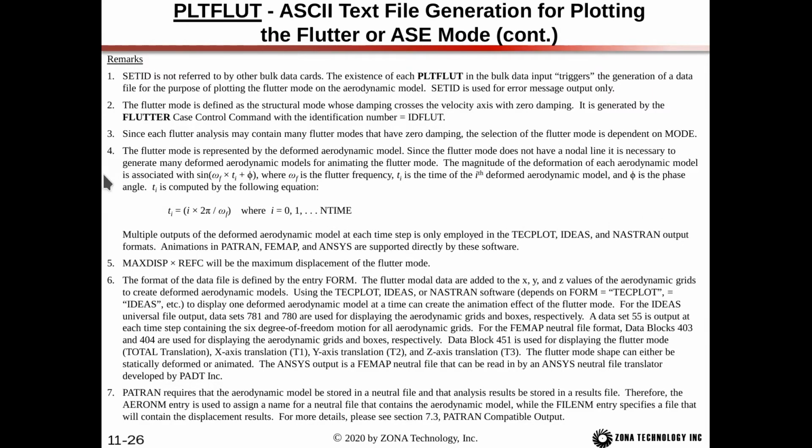So skipping down to remark 4 here, the Flutter mode is represented by the deformed aerodynamic model. Now, since the Flutter mode does not have a nodal line, it's necessary to generate many deformed aerodynamic models for animating the Flutter mode. The magnitude of the deformation of each aerodynamic model is associated with sine of omega f times ti plus phi, where omega f is the Flutter frequency, ti is the time of the ith deformed aerodynamic model, and phi is the phase angle.